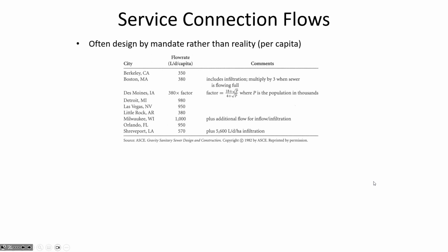and it would be related to the entire area of that business's roof. So when you are trying to estimate how much water is going to come into the sewer, there's on the one hand the reality of the situation, which as an engineering estimate would be related to the number of people that are there, related to the quality of the pipe that's put into place, the age of the system. But in a lot of places there's also municipal regulations that tell you what to assume, so that you actually don't have the flexibility to size the pipe based on how much water you think there will be. You just size the pipe based on what the guidelines tell you to assume.